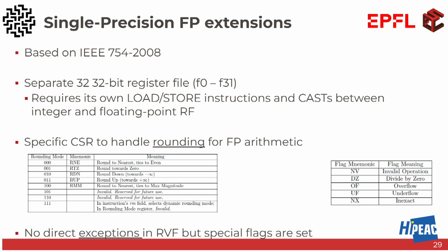No, because they target the integer register file, correct? So the load instructions will activate a finite state machine in the CPU that emits an address to the memory, gets the answer from the memory, and stores the data into the integer register file. So I need something else.